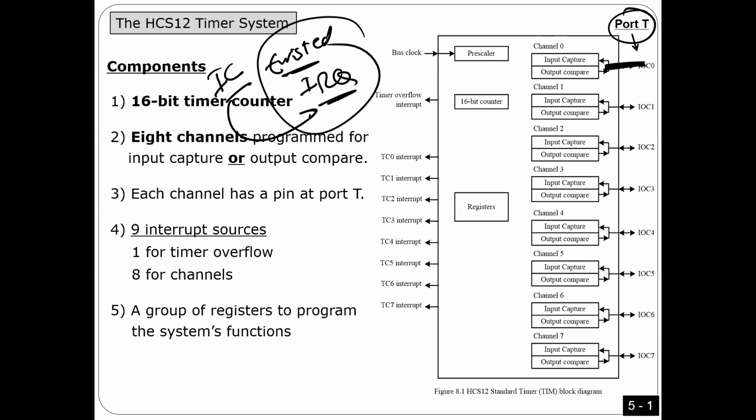Also, I can twist output compare to be like RTI. So now you can have also 8 RTIs. Again, listen to what I'm saying: here I'm not using it as output compare. Here I'm not generating a signal. I'm saying I'm gonna twist it, as you will understand later.